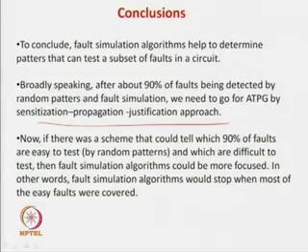Now we see that experimentally it has been found that this procedure of random pattern based fault generation can help only with about 90% of the faults. The remaining 10% of the faults are generally hard to detect, and for those you have to go by the sensitize, propagate and justify approach. So, in the next lecture we are going to see that if somebody or some algorithm can tell you that these 90% of the faults